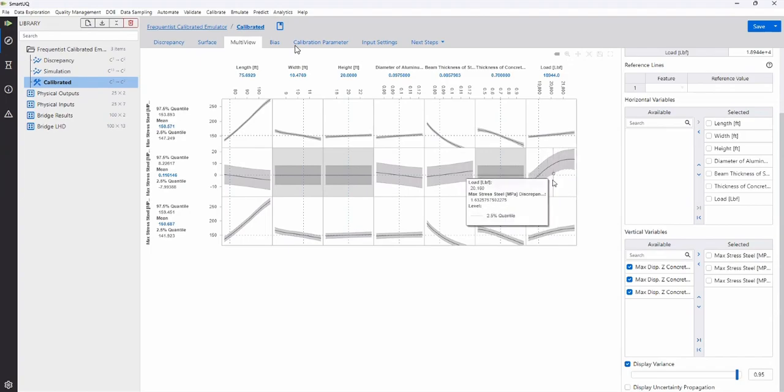As we increase this load, we have to add a larger and larger value to that simulated result to get what happens in reality. So we're increasingly underpredicting the result. And that could spark some intuition in the engineer, in the person that's working on this problem. What assumptions did we make in the underlying simulation that might lead to behavior like that? And perhaps you can go back and improve the underlying model.